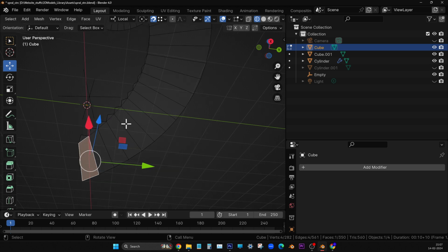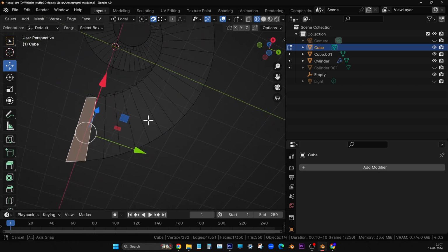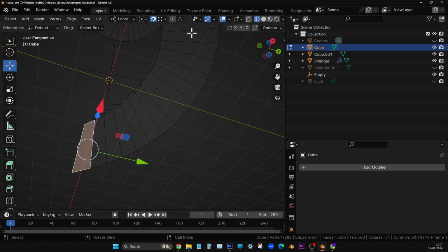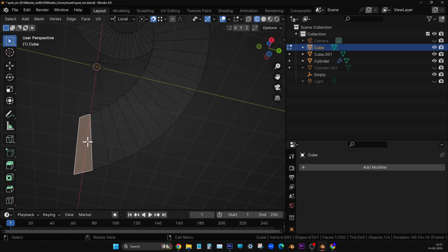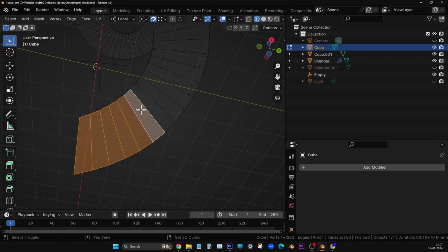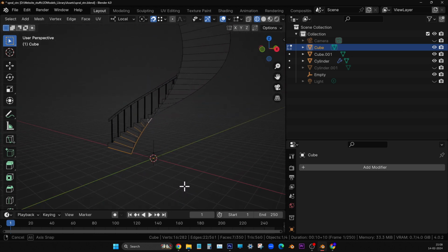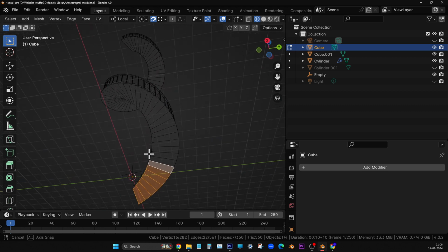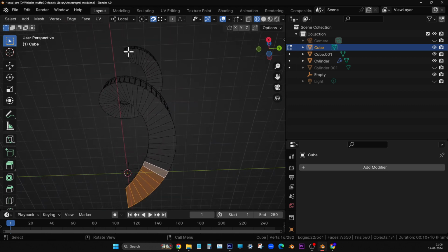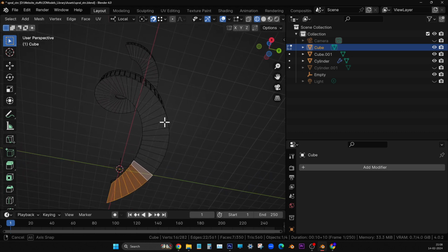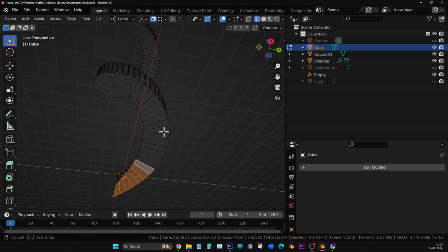so I have to make it a little fat in the bottom. For that I'm going to extrude it. Before that I have to first select, only then I can extrude it. Now I have selected the first one and I'm pressing shift, selecting the next one, like this. But it will take a long time if I start selecting like this for so many, like I think 70 or 65 something we duplicated. So 65 faces I have to select, it takes time.